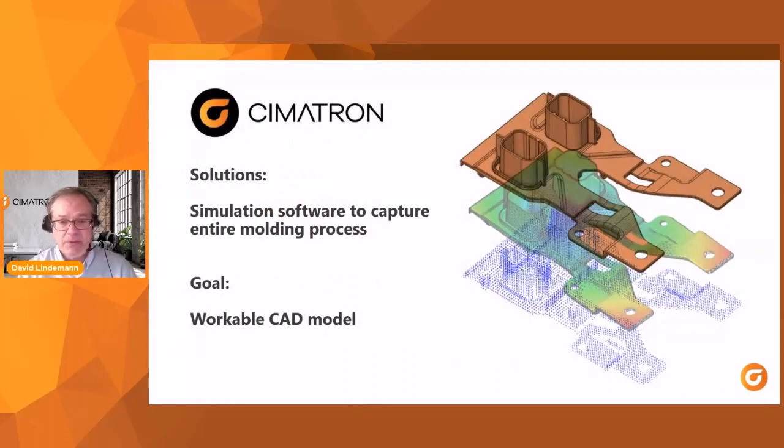So the solution we're looking for here is to have the software capture all that. We know the process. It's going to reflect in the tool, the way we tool for that warpage. And at the end, we need to have a workable CAD model, not just an STL, but that CAD model, so that we can do our mold splits, pull our inserts, and do all the design work.